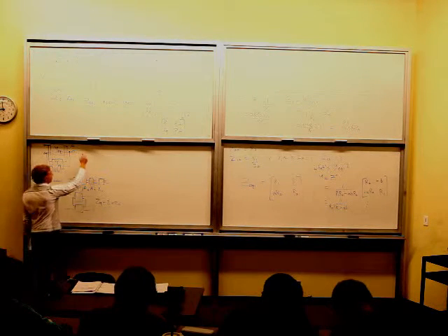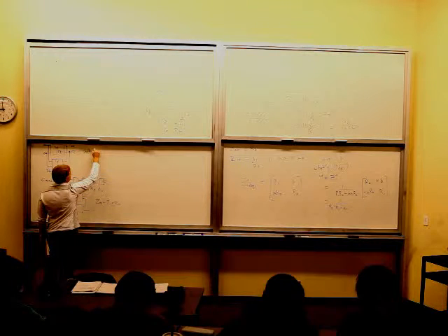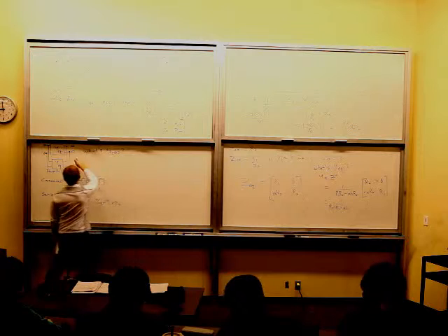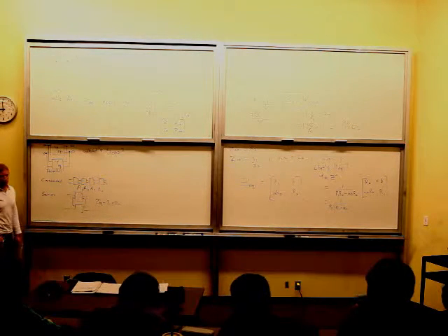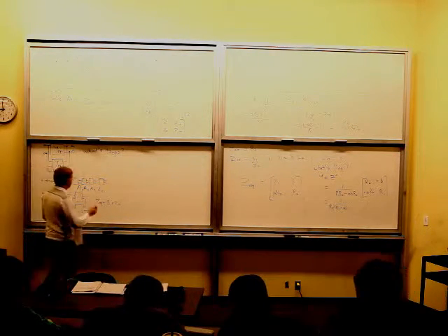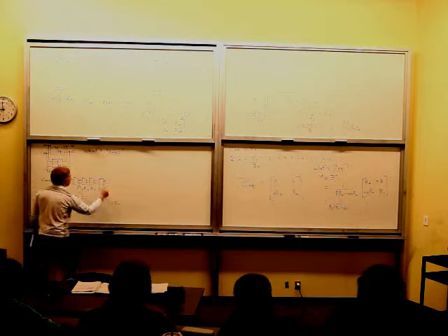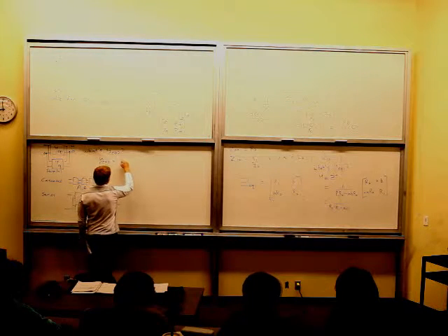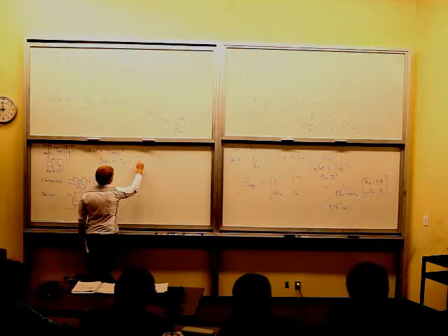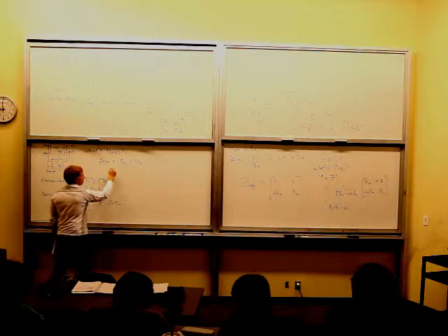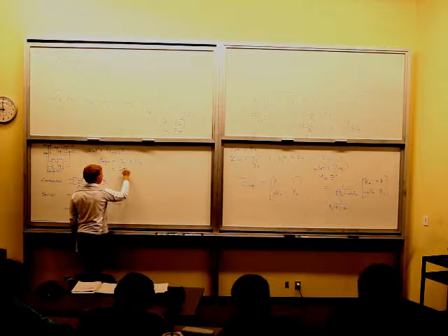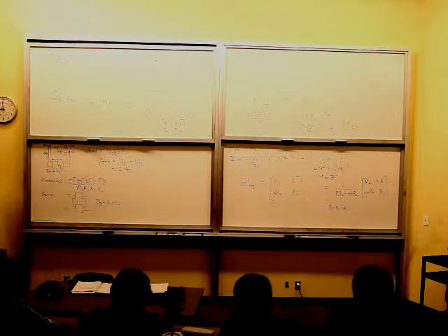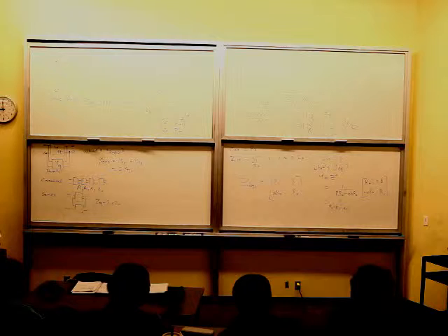So the question would say, what's the equivalent Y matrix? Y equivalent 2, based on these connections, what's a two-port network that looks like those two? And remember, you add your Z's, you add your Y's as well. So Y equivalent 2 equals Y equivalent 1 plus Y equivalent 1. They're identical, so it's just a scalar value of 2 times each one of those. That's a parallel connection. Use Y's for a parallel connection.